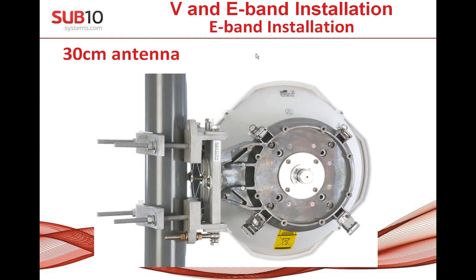There is a question coming, and it was a good question. On the paper you have some lubricant which is coming, and the lubricant is good to put on this antenna. You see there is the gum O-ring which is doing again some protection from the water, and it's good to put this lubricant around this ring to be sure that water is really not able to go in.